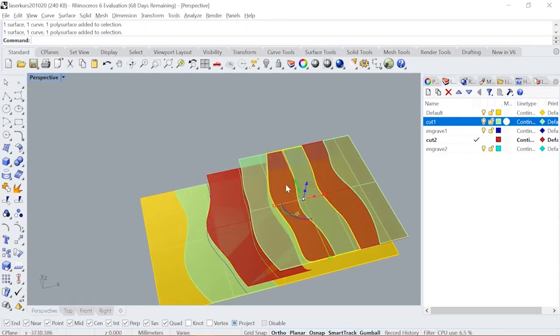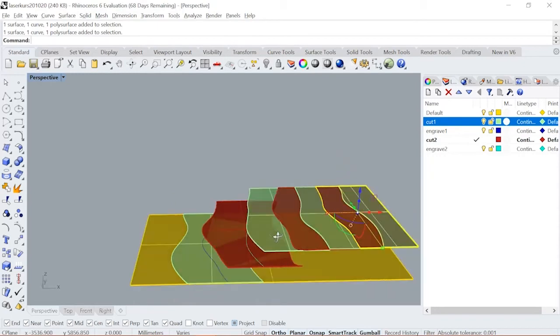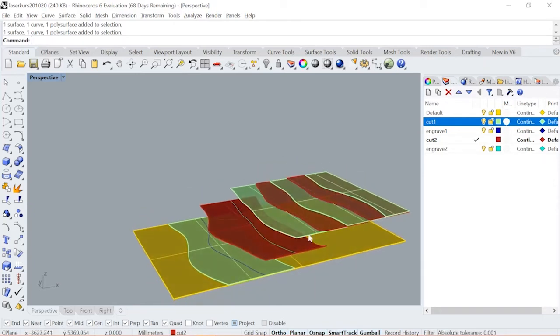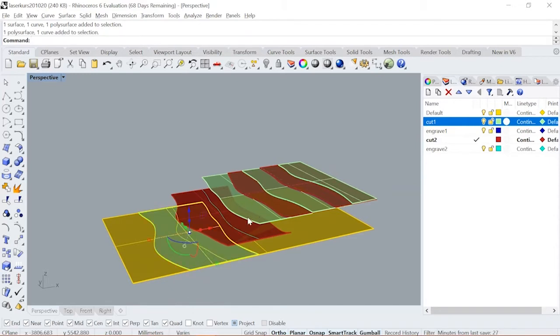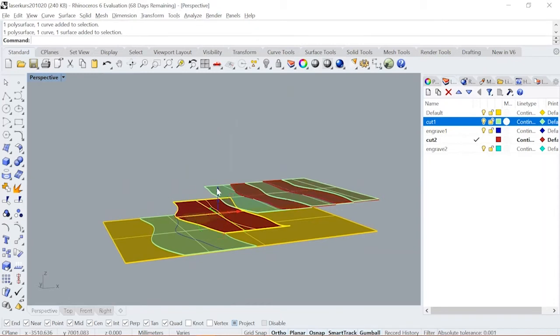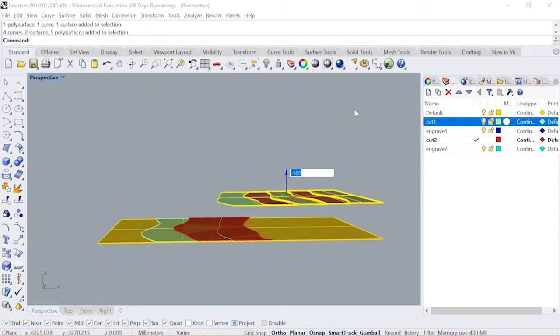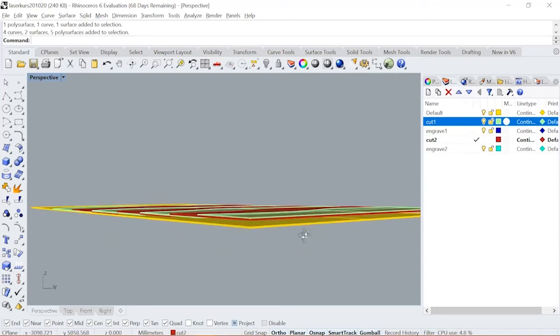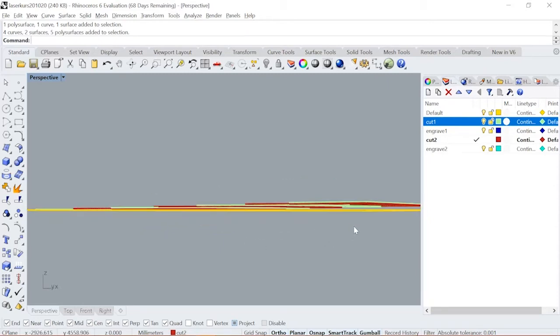And then we have the red ones that are going to be the second cutting file with the blue lines for engraving. Engraving is just not cutting through the material, it's just marking on the material, not cutting entirely through. So when you've cut these, you put them one after another on top of each other, and it's good to have the engrave lines here so you know where the next file is going to be placed. And I've put these 100 up. So you put them like so, and on the end here you're going to have a gap, which you can close with timber or material or candy or whatever you want to use.